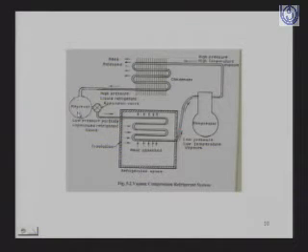Then the receiver, where we store the liquid. Then through the expansion device they come to the evaporator. This is where they absorb the heat from the place where we want to keep the cold, and then they go back to the compressor.